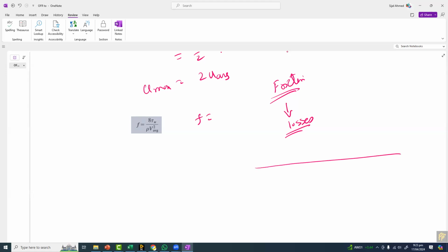So when the pipe flow is going in one direction, because of the wall effects, the roughness and the Reynolds number, this will introduce losses. So a pressure drop will be there. This is because of the losses coming from the friction effects. So this value will give you the pressure drop along the pipe. That much pressure drop you have to compensate by the pumping power. So you have to put a pump that can counter the pressure drop occurring because of the friction effects in the pipe.